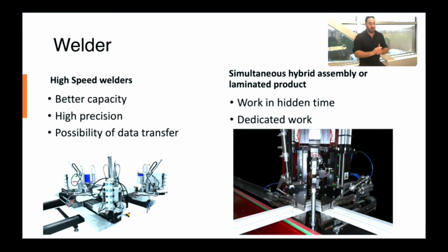So if you're thinking about a 1000 millimeters or 1 meter frame or sash, you're going to be cutting it a little bit longer, so to 1006 millimeters, burning 3 millimeters on each side, and then you're going to have your 1000 by 1000 at the end. But for all the good reasons, you could be having problems with your saw, you're cutting too high or too low.